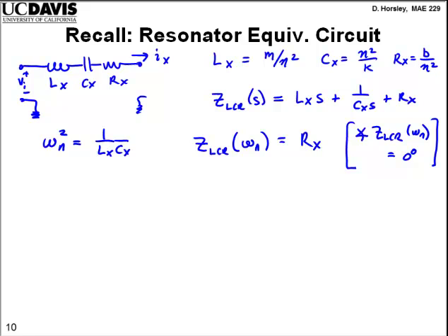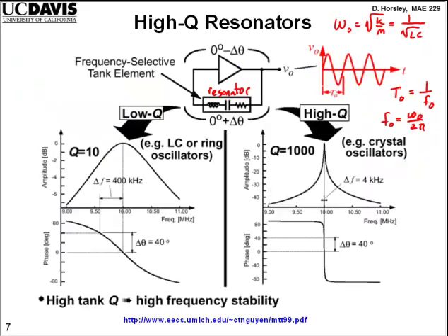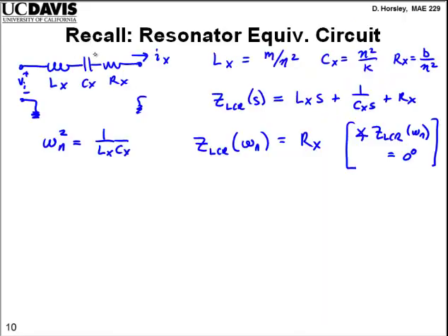And at low frequencies, just like it shows on this slide, we have plus 90 degrees of phase, and above the resonance we have minus 90 degrees of phase. One way that you can think about this is that at low frequencies, like for DC, the impedance of the capacitor dominates, right? It looks like a very high impedance. The inductor basically looks like no impedance. And so at low frequencies, this looks like a capacitor, okay? And then at high frequencies, the opposite is true. The capacitor kind of looks like a short, and then the inductor dominates. And so we could say that at resonance, it looks like the resistor. At low frequencies, it looks like a capacitor, and at high frequencies, it looks like an inductor, okay?